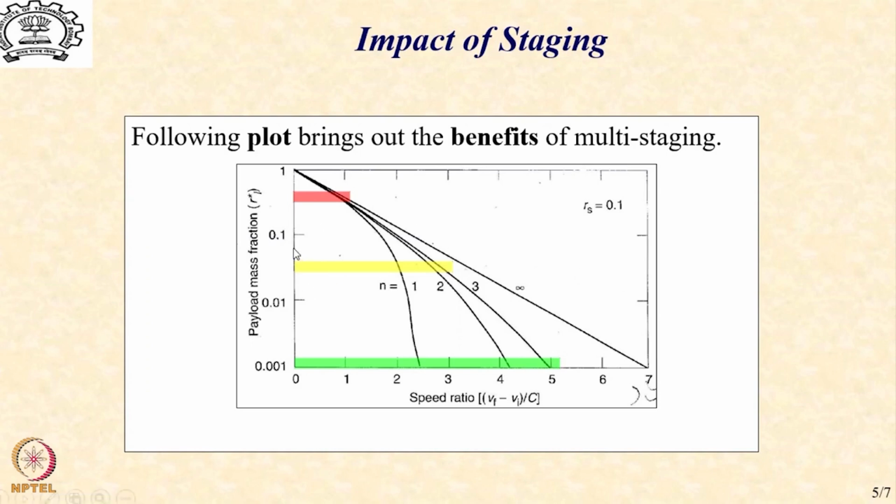So let us now move over to a two-stage operation. Now, immediately I see that for two-stage operation, the velocity will be of the order of 7600 meters per second, and we can establish an orbit. Which means that if I want to launch a 70 kg of payload with a 1000 kg rocket, I must have at least two-stage operation. Of course, if I go to a three-stage operation, there is only a marginal benefit in the velocity.